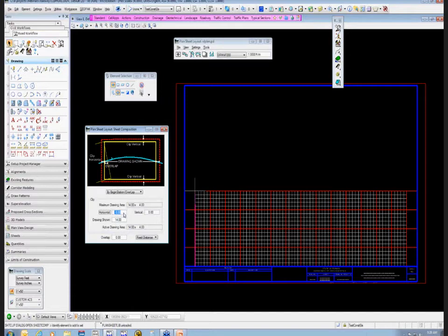how do you explain this so it makes the best sense? It's like a margin on either side, if I'm talking about horizontally and vertically, creating a margin within this drawing area. It got the maximum drawing area from the sheet library, and it's going with the smallest one here because that was the profile area. When it goes to create this clip, it takes this into consideration, and it will make your drawing area and the amount shown smaller.